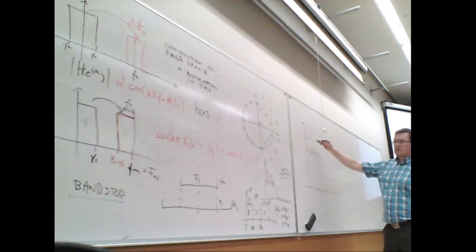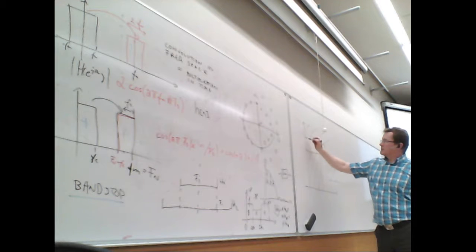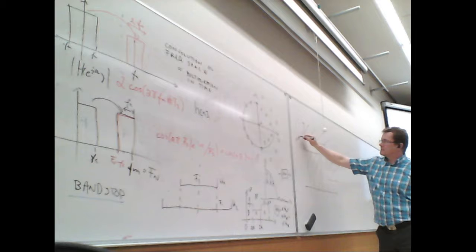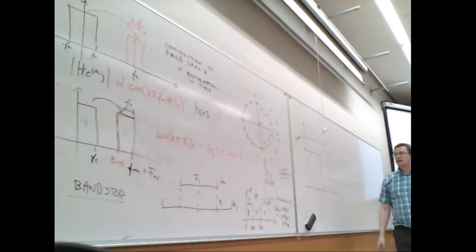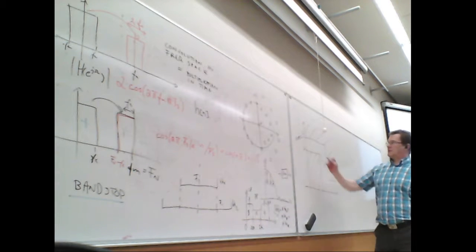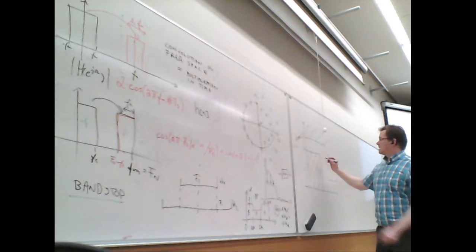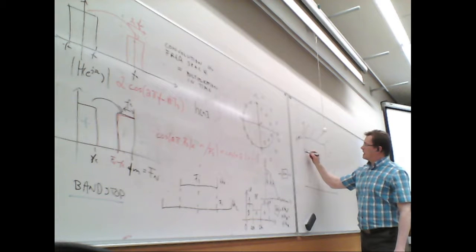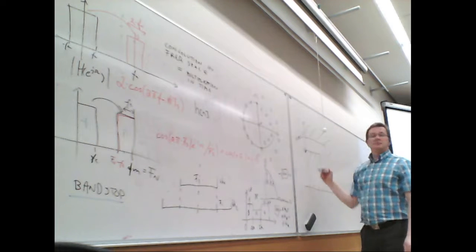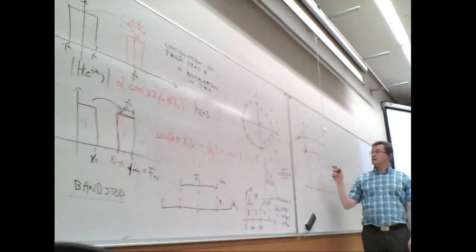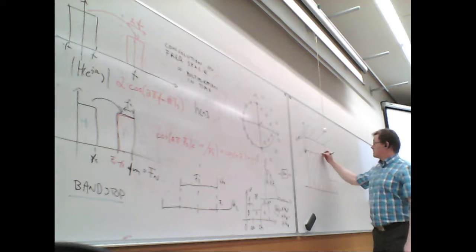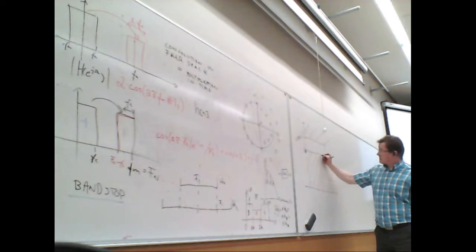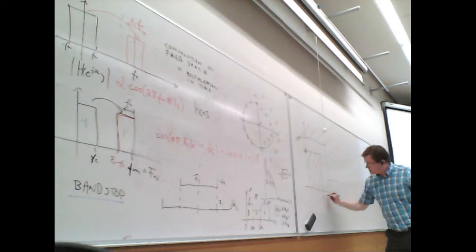So passband ripple: this is 0 dB, and this is the ripple of the desired response. If there's 0 ripple, then for 0 ripple systems you would have minus 3 dB as your cutoff level. But for any other, you would use the ripple for the cutoff frequency. So that point actually defines the cutoff rate.